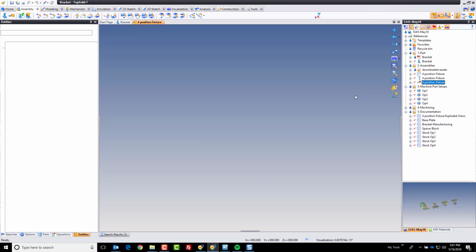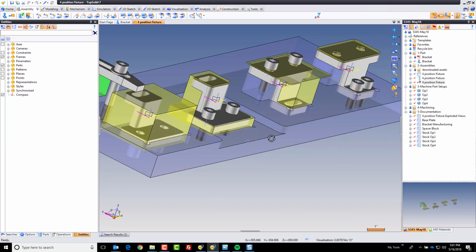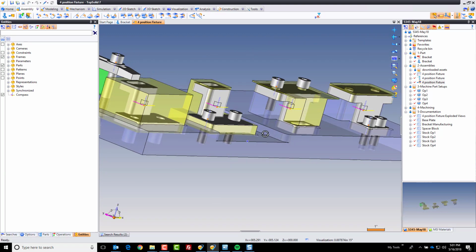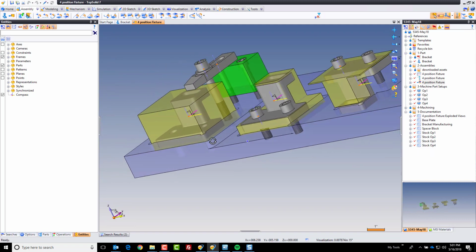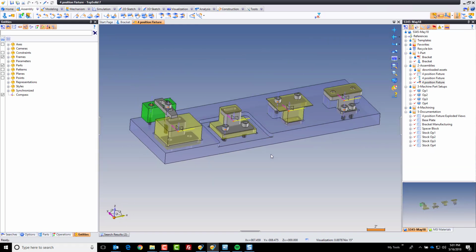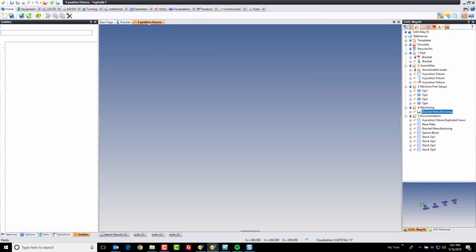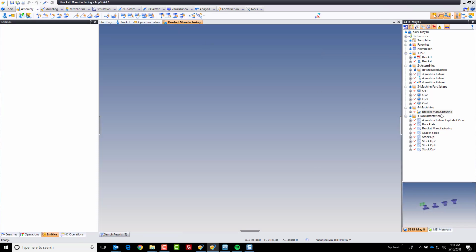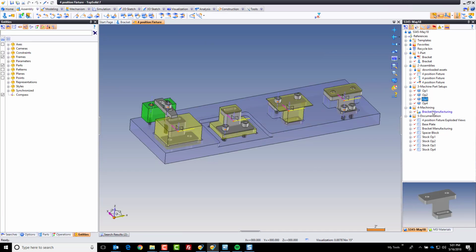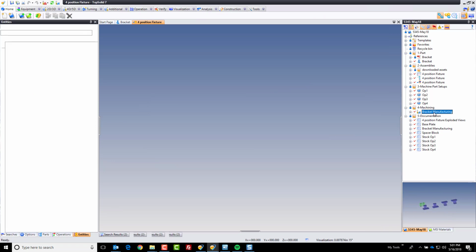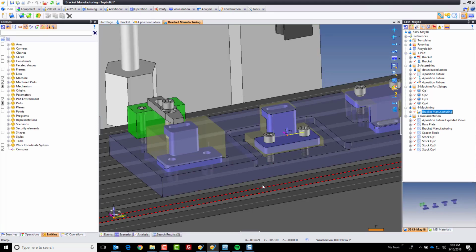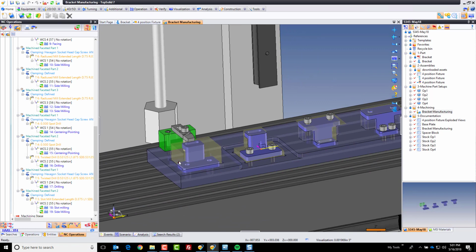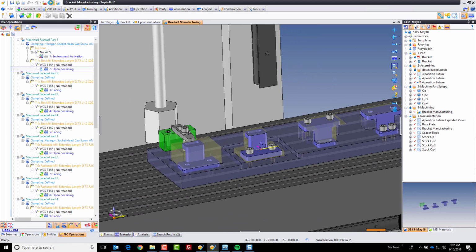If I go here and I open this assembly, notice everything is up to date. Everything got taller as necessary because we designed everything with the right design intent. If I come down to my machining, the only thing left to do on the machining, and I should point something out here, is the CAD data was updated, but notice this is blue. Blue tells you that you have something inside the document that needs to be manually regenerated, and that, of course, is the toolpath. The toolpath we will never automatically regenerate. You have to open it up and just hit this button.